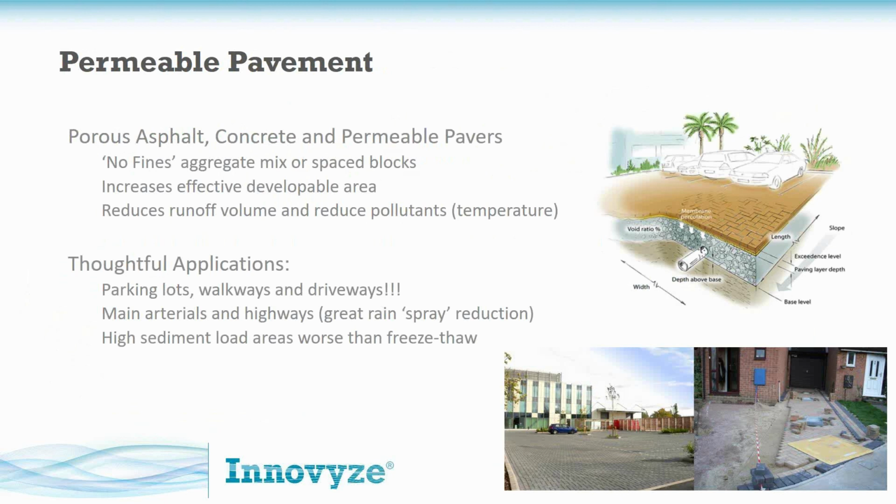The important item here, though, freeze thaw, a lot of studies on this. Might be the first one I always think of. Actually, it's nowhere near a factor. Sediment load is a factor, right? So if you don't educate the community, don't have signs for kids to understand different languages, you might have someone dump soil on a site, and maybe they're having a project and they're moving dirt. Well, if you put dirt on top of these porous structures, you're just going to fill it right in, and there's no vacuum truck that can get it perfectly cleaned out once you do that.